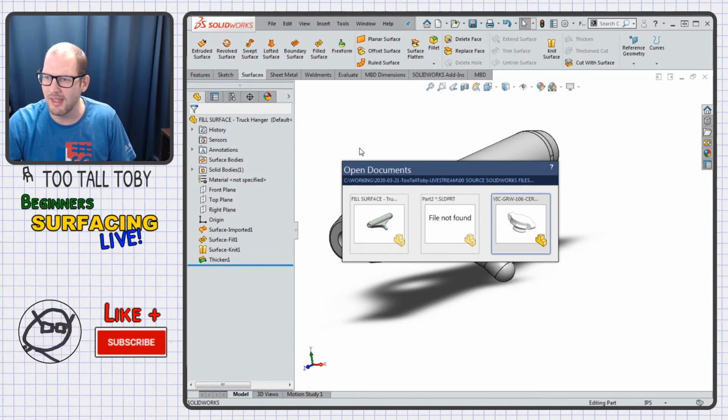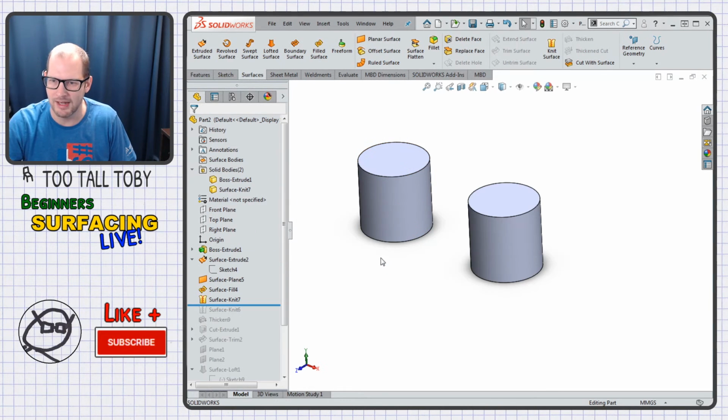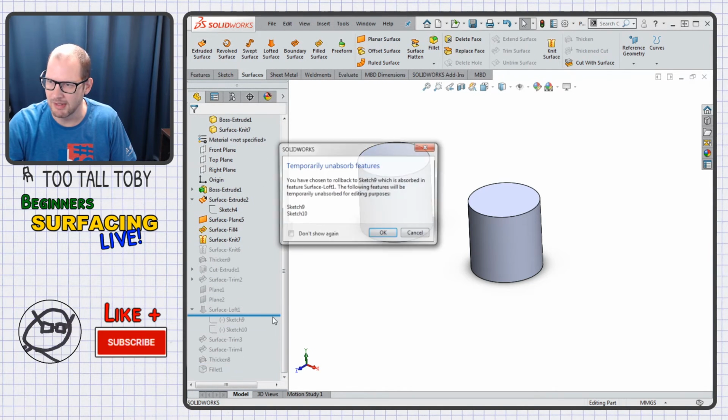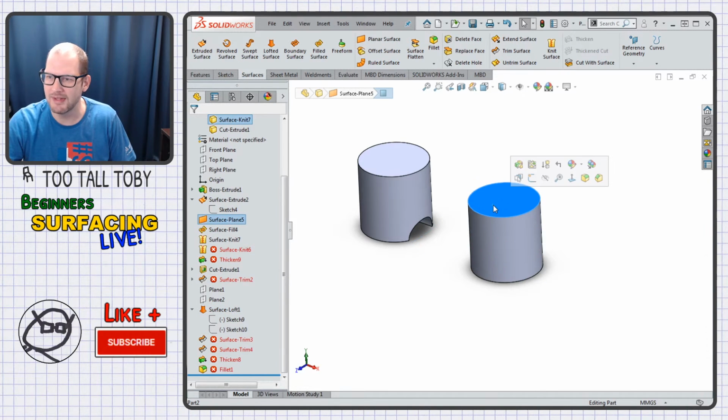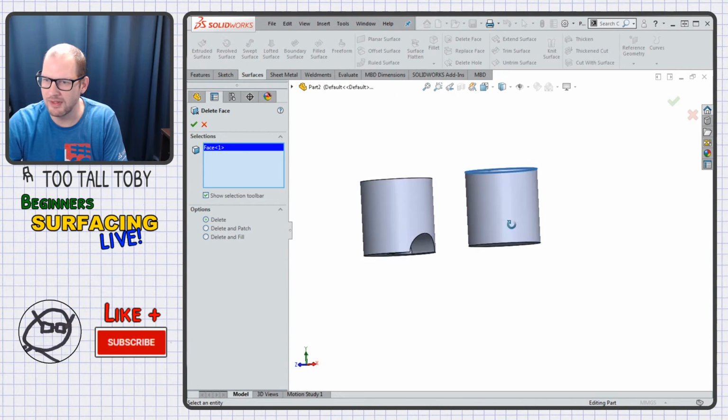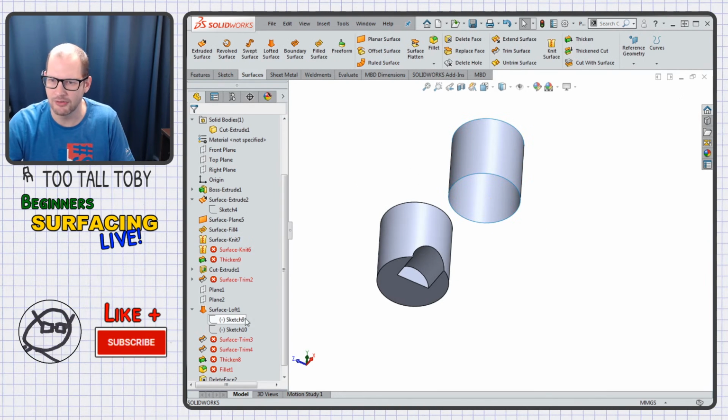When you're doing that face shield example that I showed here a little bit earlier, when we did that surface loft example, this is probably going to be all screwed up now. So here's that surface loft. Let me take this and I'm going to do a delete face. So I'm going to delete the top and the bottom of that solid. That turns it into a surface.